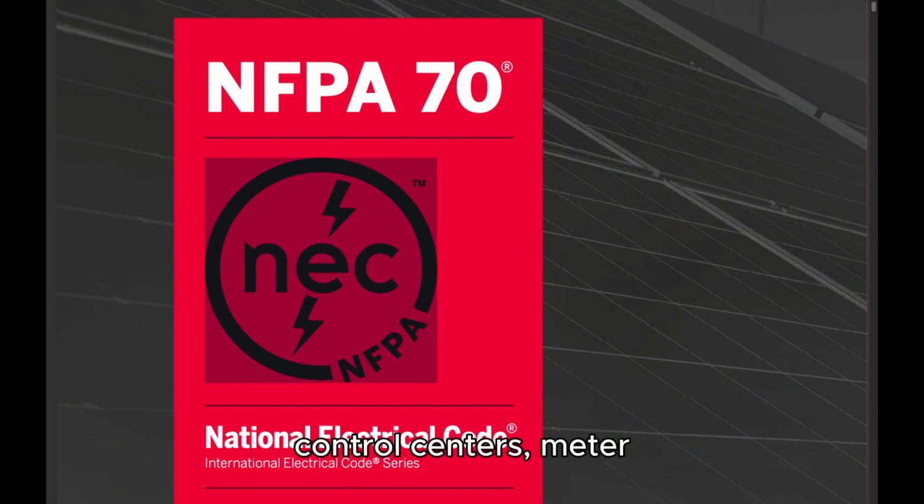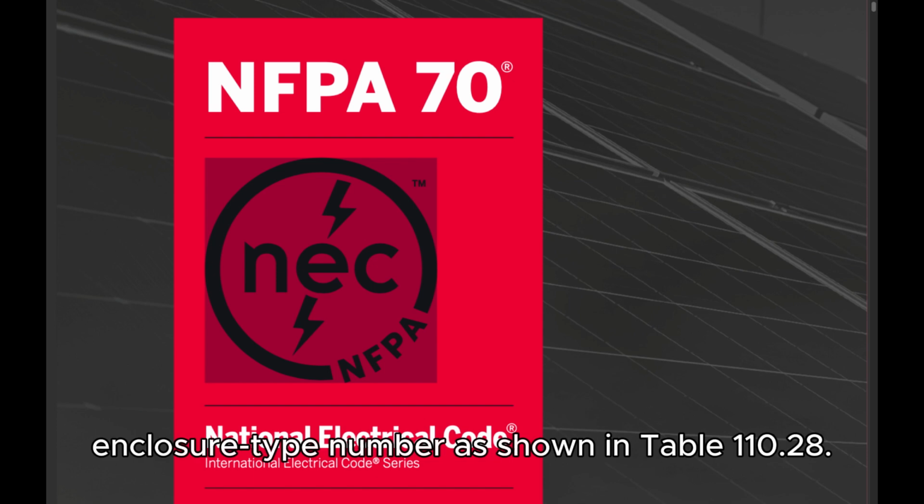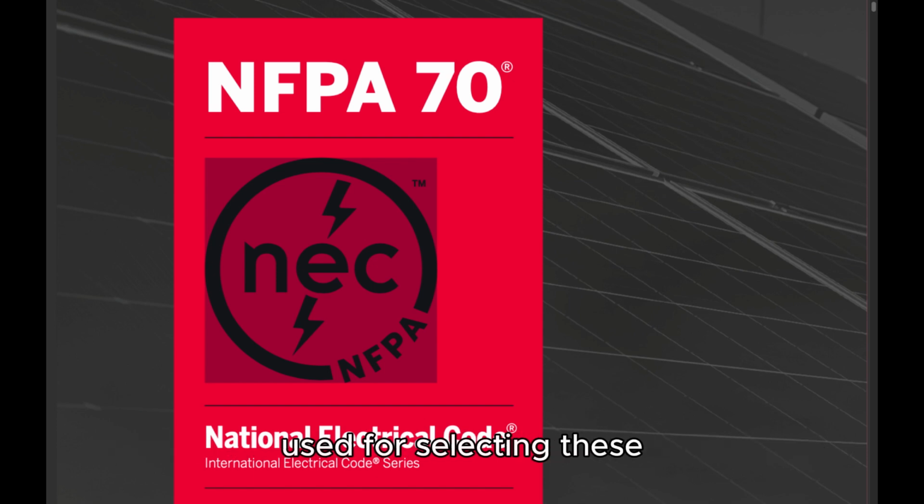enclosed switches, transfer switches, power outlets, circuit breakers, adjustable speed drive systems, pullout switches, portable power distribution equipment, termination boxes, general-purpose transformers, fire pump controllers, fire pump motors, and motor controllers, rated not over 1000 volts nominal and intended for such locations, shall be marked with an enclosure type number as shown in Table 110.28. Table 110.28 shall be used for selecting these enclosures for use in specific locations other than hazardous (classified) locations.